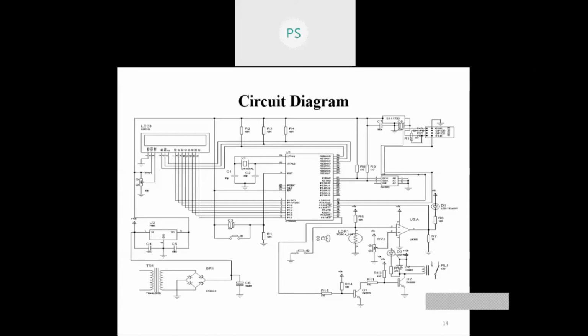In our project concept, the microcontroller needs to get the pulse from the energy meter. To get the pulse, we could use a wire to connect from the pulse output to the microcontroller I/O pin, but it is not safe. To protect the circuit from spikes and electrical noise, we are using an optical signal to get the pulse. If we use an optical connection between the energy meter and the microcontroller unit, it will not only prevent circuit damage, but also not tamper with the energy meter.